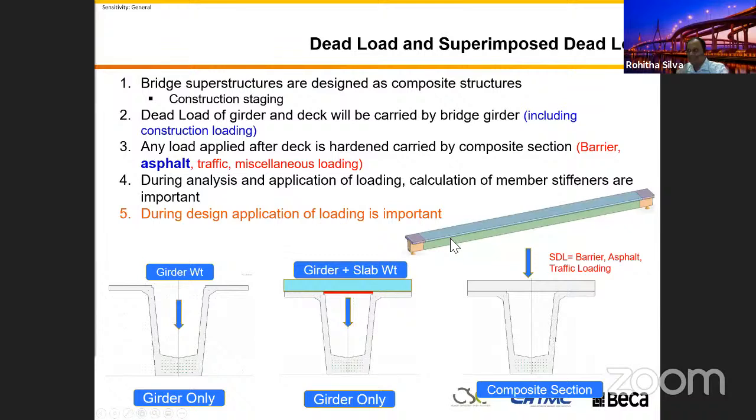In addition to that, girders have a big camber, significantly large camber. For example, this bridge, we can have up to 60 millimeter camber. When we build the bridge deck in the 30 meter length, that camber will have a significant effect. So you need to put additional concrete to take into account the hogging effect. That is very difficult to estimate, but you need to guesstimate.